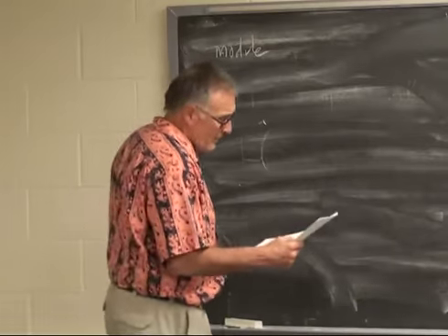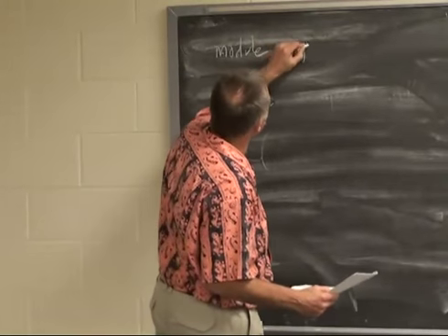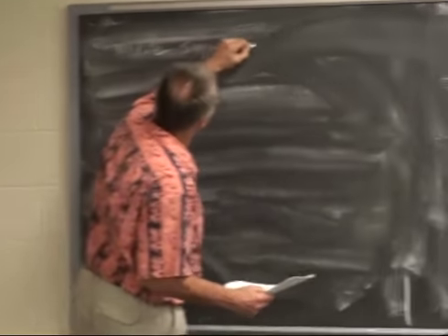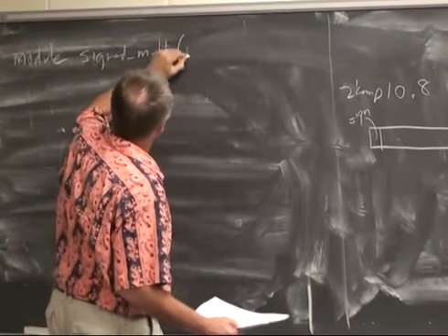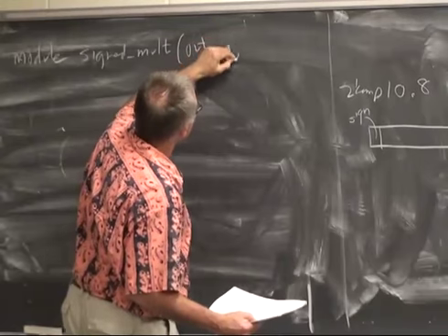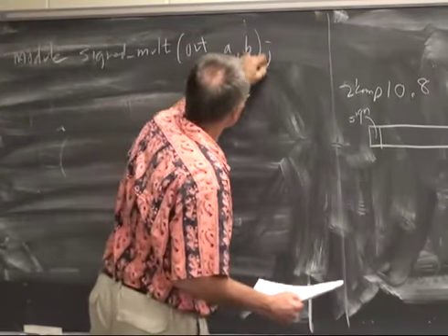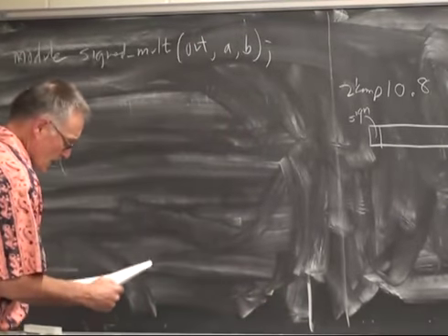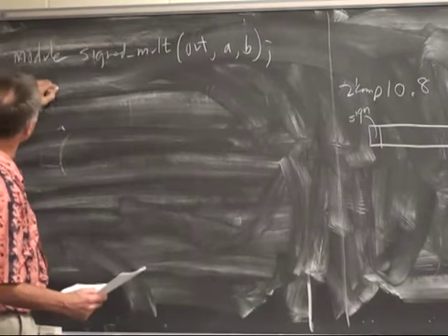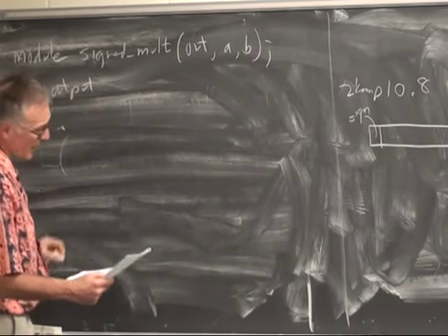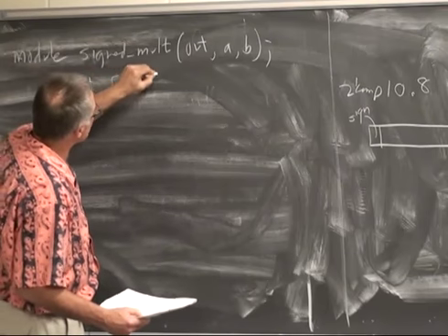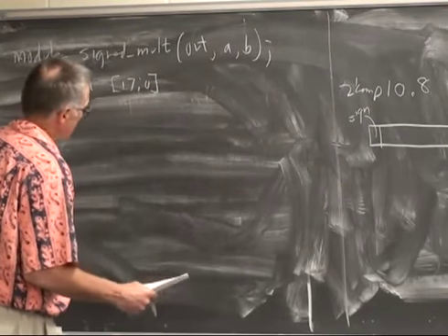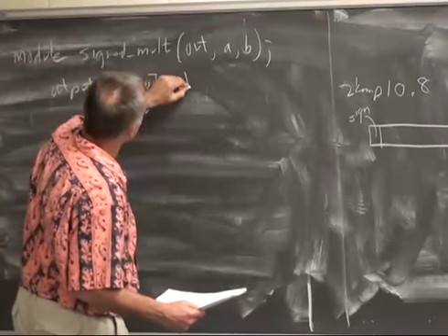So the multiply module has just 3 parameters, an A and a B input and an output. And because we're using an 18-bit system, you might guess that this would be an 18-bit output, and you'd be right.